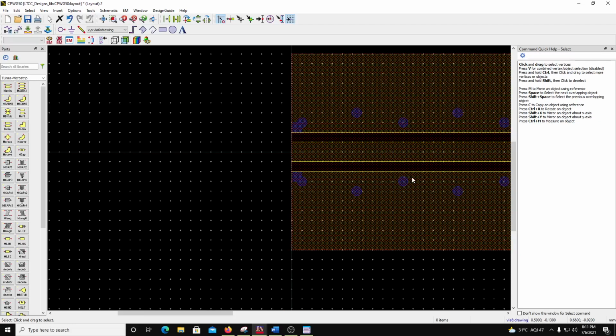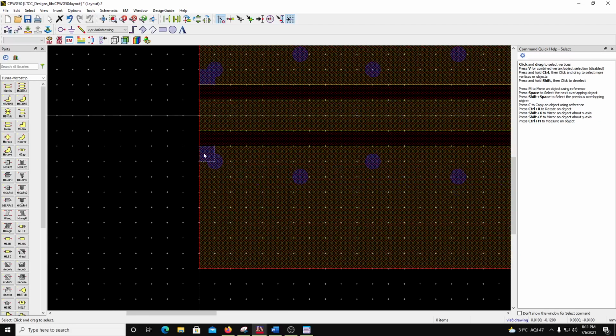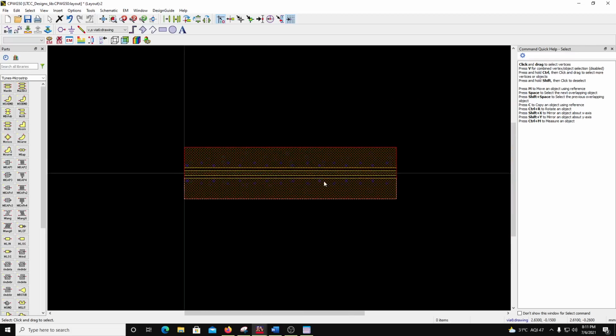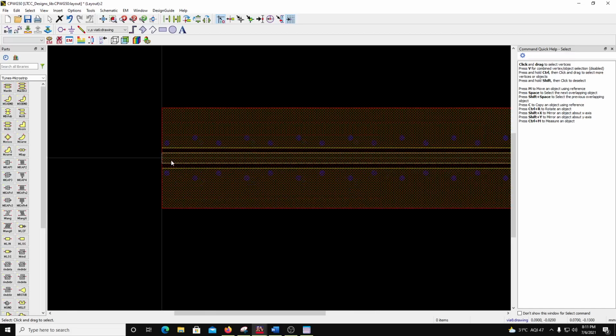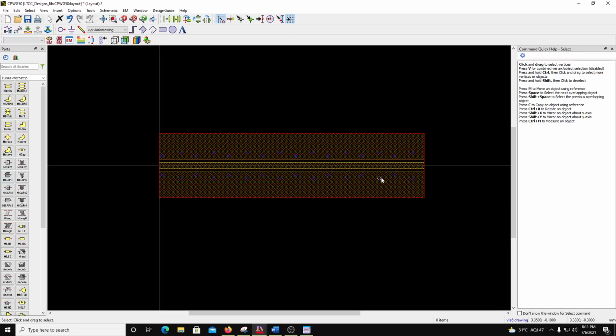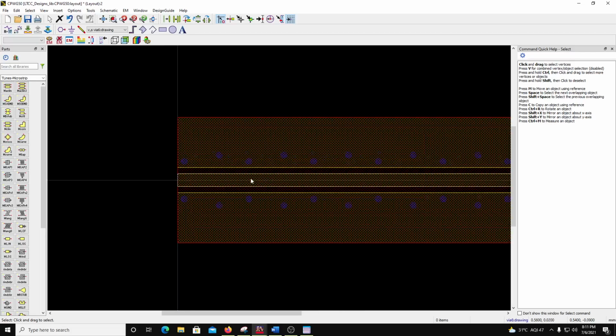So I have created a symmetric structure around this of via and get rid of that and that. And you see my vias are tying the coplanar grounds down to the ground on metal 6. So this is a structure of a coplanar waveguide, and I'm expecting that everything is okay to give the right 50 ohm impedance, right? So now I'm ready to put the ports.